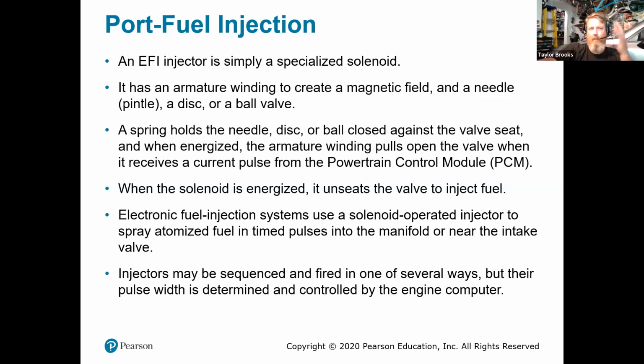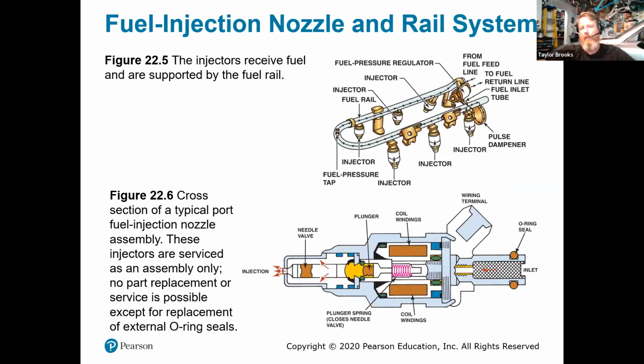The phrase for it is typically uncapping fuel injectors. Like I said, that's getting too far, where the injector could spit its guts out, and those are all hardened parts that are not going to bode well for the internal combustion components inside of that engine.